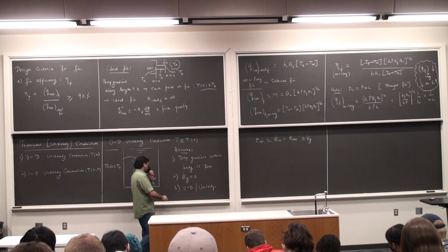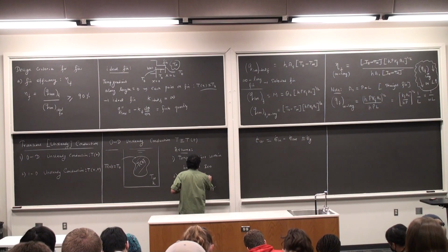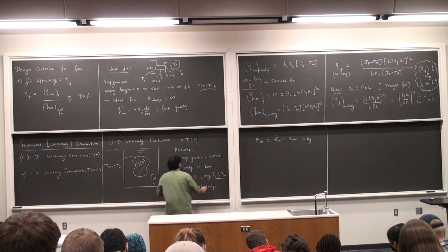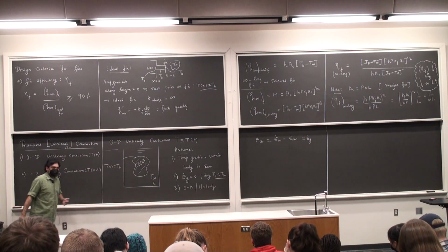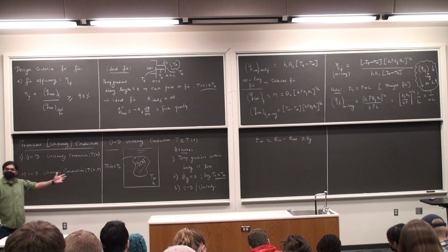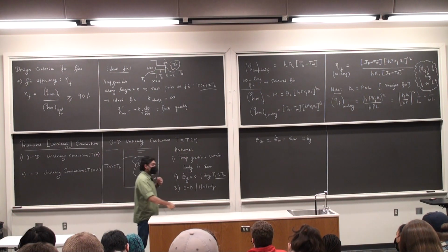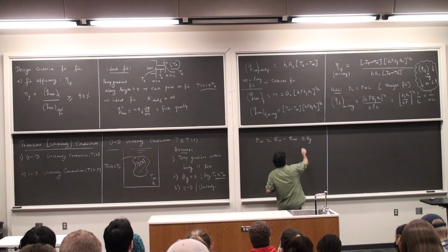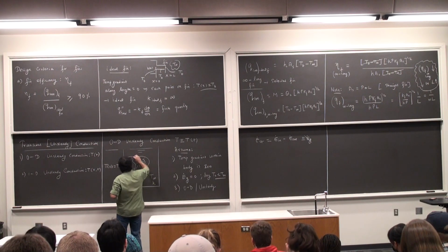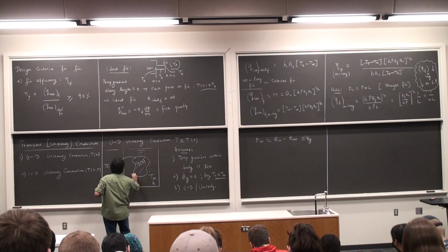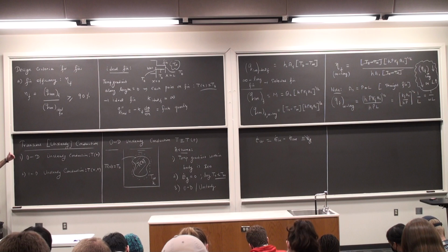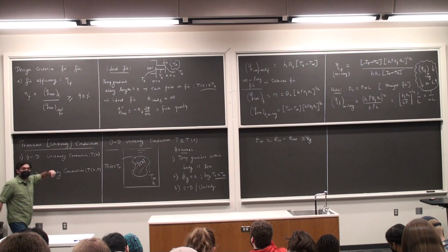Okay, so another assumption, which means that after a sufficient finite amount of time, the temperature of the block is going to be equal to the temperature of the ambient fluid. Okay. Alright, so here I'm going to cancel off this. If I draw a control volume, a control surface around this body here, all I'm saying is that there is going to be some convective heat transfer into the body. Right?